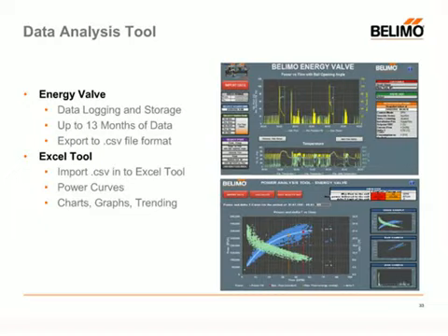Again, something that's very powerful in case design delta T is not the optimum delta T. This here will allow you to suggest a set point based on current conditions. And some of those things that take effect that we talked about earlier, the inefficiencies within the system, within the coil, valves being oversized, so on and so forth.